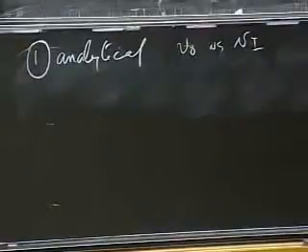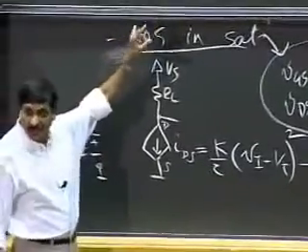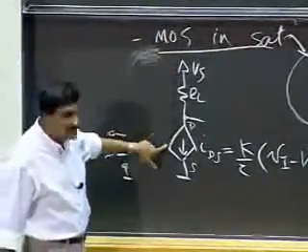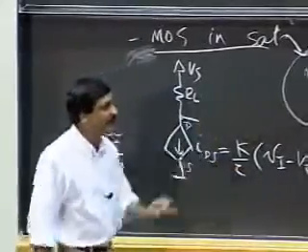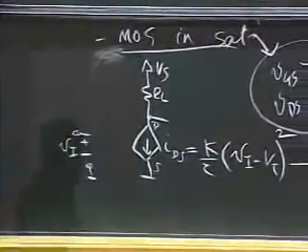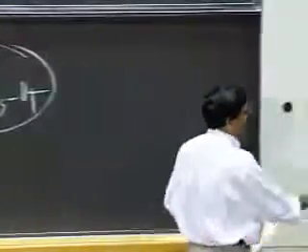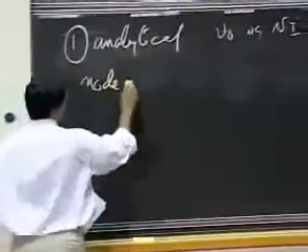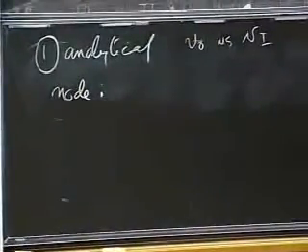My goal will be to obtain V naught versus VI. So again, remember, where are we here? The MOSFET circuit, operating in saturation. So I can replace this with a current source. It's nonlinear, and so I can apply one of the two methods, the analytical method or the graphical method. Let's do both and start with the analytical method. The analytical method simply says, go forth, apply the node method, and solve, right? Simple stuff. So let's go ahead and do that.